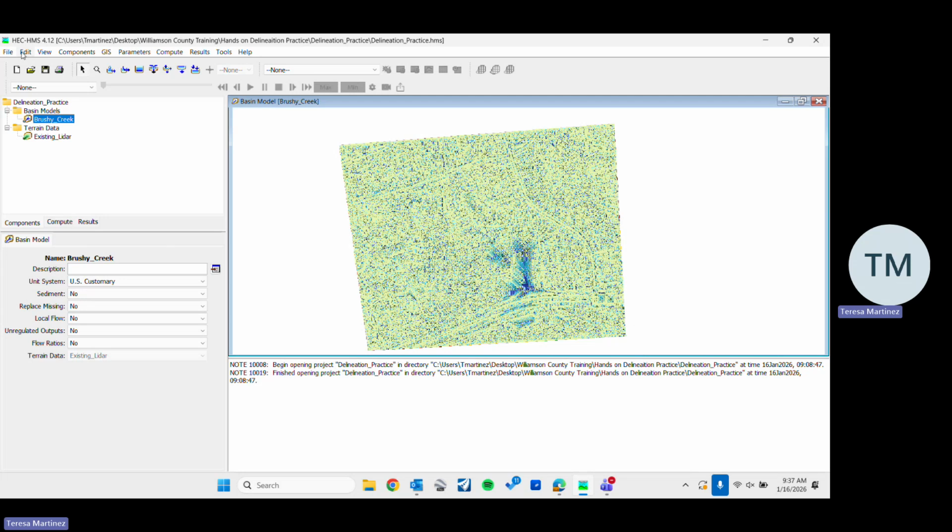When they're doing the processing, after they do the flyover, they collect all the raw signals, the reflectivity, or the rebound signal. Like you mentioned, if there's a tree, the tree's going to bounce the signal back first. So when they're processing the raw LiDAR data set, they have a certain algorithm that will read for the tree.